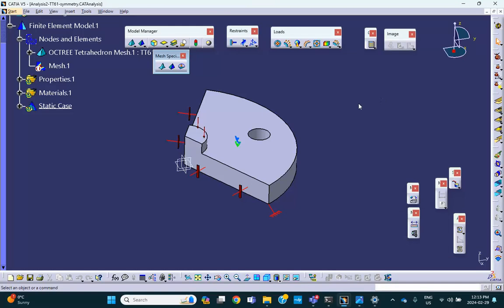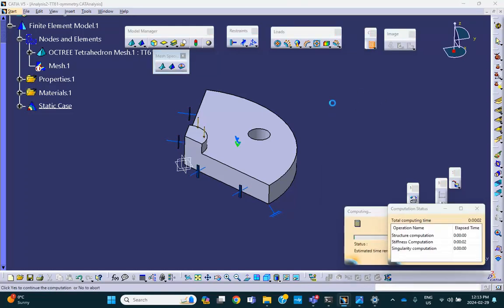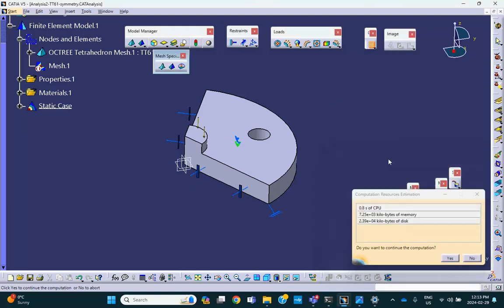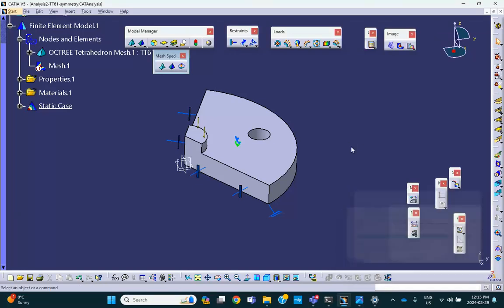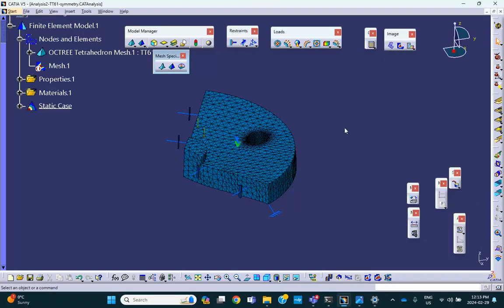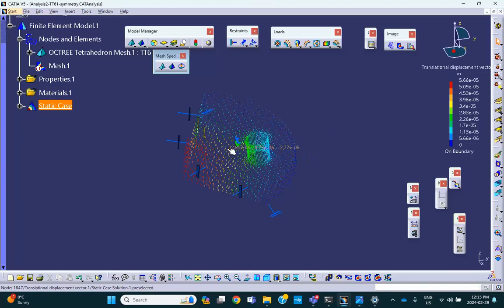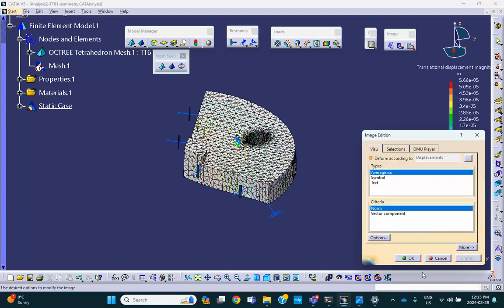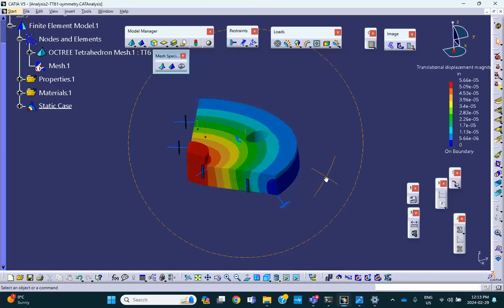All right. So we're going to run it. Don't worry about this warning message. It has to do with that slider that you put in there. We got the same thing when we did the full model, and that's it. So look at the deflection. That's the way it should be, right? That's the way it should be. Here's the displacement. The result should be reasonably close as long as you have a good mesh. Again, we are not assessing accuracy here. We are not trying to compare this with the previous run that we did, because there's more to it than we are doing in this one session, basically.